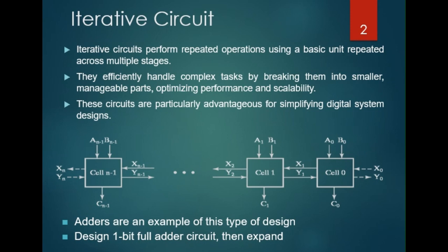Why? For this kind of design, we just design one slice circuit, and then we just need to duplicate it several times, or n times, to implement an n-bit circuit. Adders are one example. You just need to design a one-bit full adder and then multiply or instantiate it multiple times to expand it into an n-bit adder.